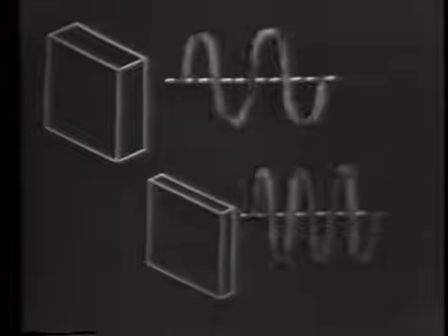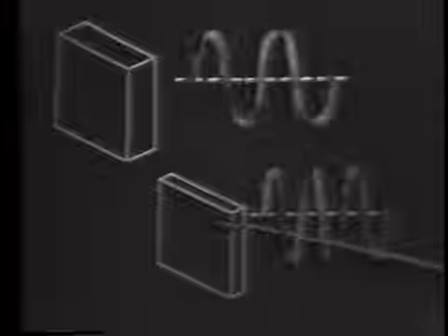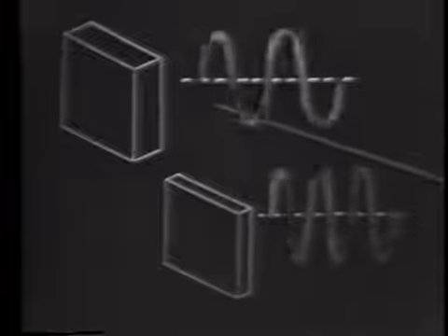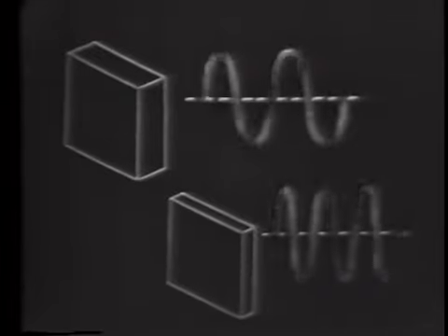Now, you'll recall earlier we mentioned the resonant frequency of the crystal. Not all crystals, naturally, will have the same resonant frequency. Its frequency will be dependent upon its thickness. Let's take a look at 2 pieces of crystal cuts and compare this difference in thicknesses. As you can see, the thinner cut here, the thicker cut here. We're indicating here that the vibration of this thinner cut, or the frequency, is greater than this cut. Now, this will always hold true. The thinner the crystal cut, the higher the frequency of oscillation.